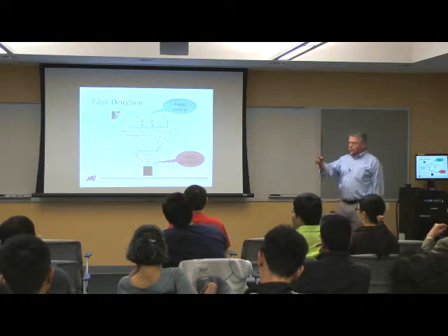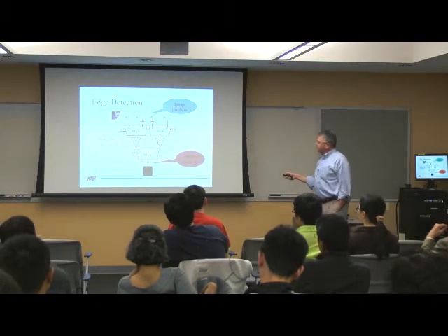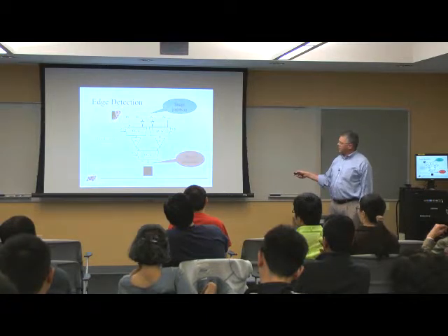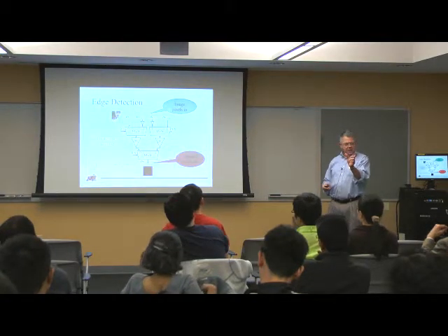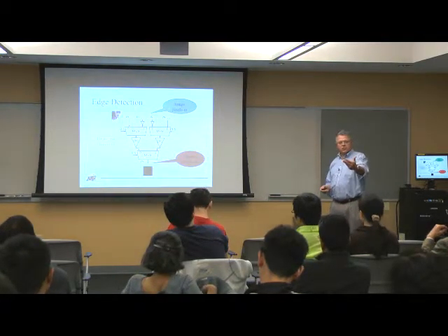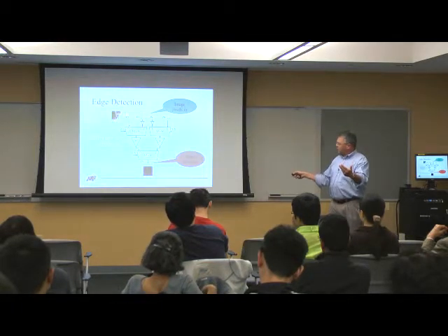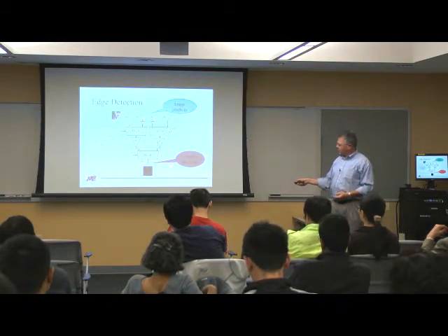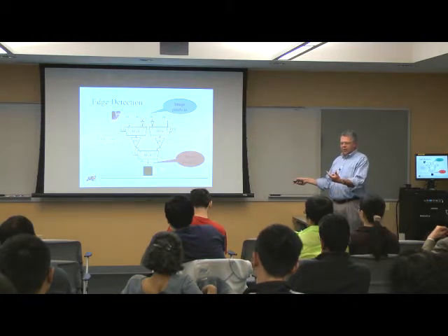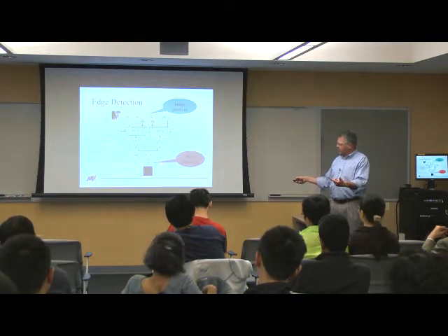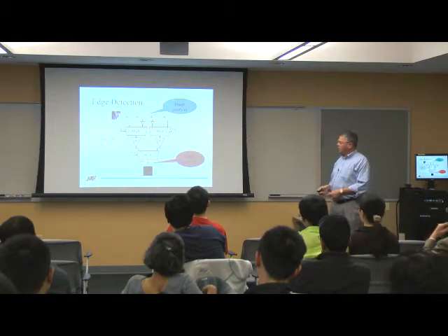So the way this works, to your question, is that for every pixel here, I somehow have this 10-bit value. I have to convert it to this stream of bits. Then I run it through here, and I have a stream of bits coming out here, and then I have to add those up. I just run them through an adder to figure out what the binary equivalent is there. Okay? That conversion at either end is kind of expensive.